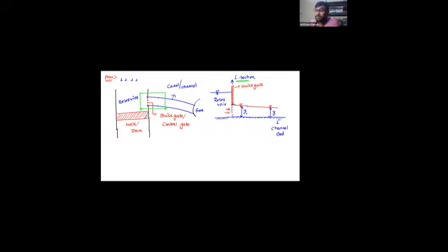So can you tell me what flow we have over here for the given condition? For the given condition, it is going to be steady uniform flow. Why is it steady? Because I am operating the gates gradually. When I operate the gates gradually at a particular section, I am allowing a single discharge and a single velocity. So at this particular section the flow parameters are constant, so it is steady flow. And along the length of the channel, if the depths are the same, so y1 and y2 are the same, then the flow is said to be uniform flow.